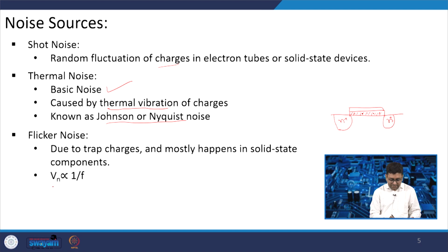This flicker noise is inversely proportional to 1 by f. So, at low frequency it is very important to consider the flicker noise. Trapped charges might be there in any solid state devices which have a different combination of materials, and the electrons will be trapped.